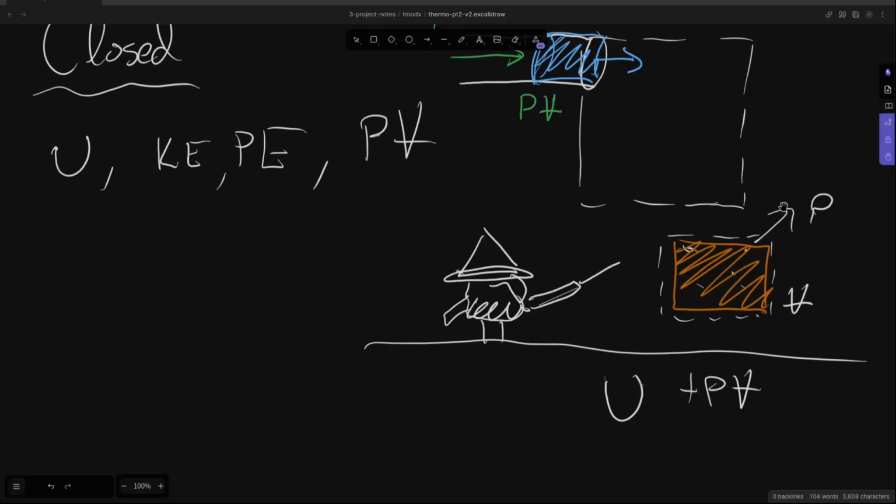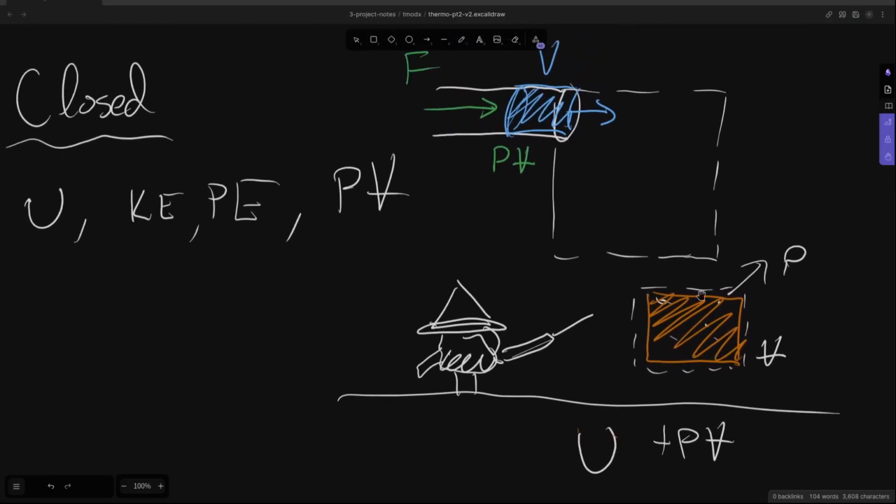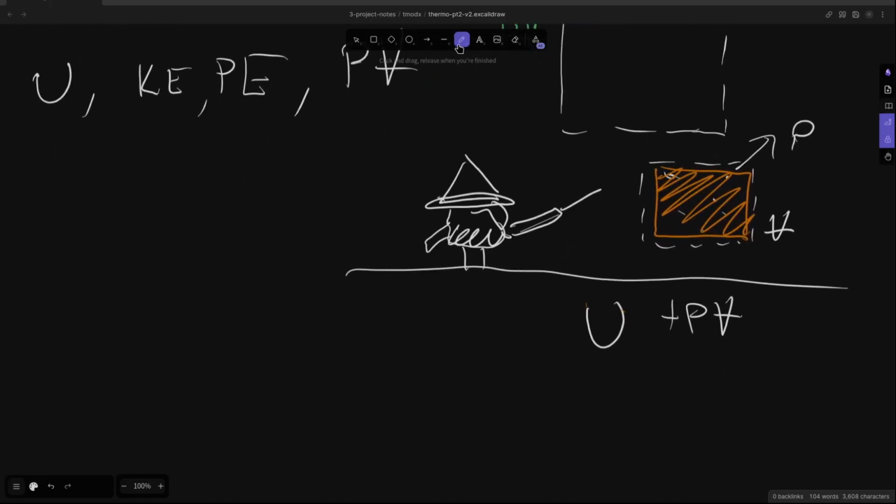So no matter which scenario makes more sense, you can think about the mass itself, or a volume and mass coming in, or the internal energy being able to draw on something at pressure at this volume. U plus PV is a very useful term, and it's part of the energy that mass draws in. It's useful enough that we define it as its own quantity. It's called enthalpy, and it has the letter H. So U plus PV is enthalpy.